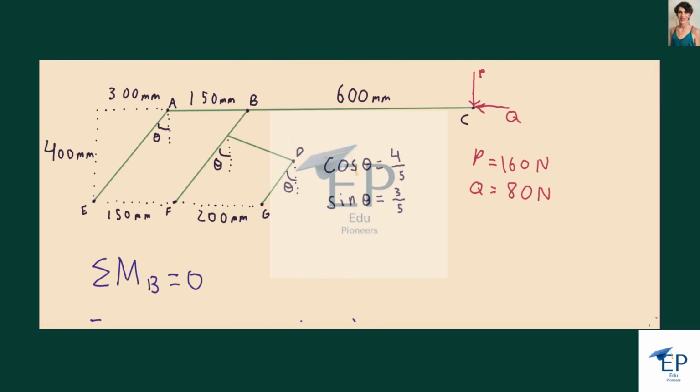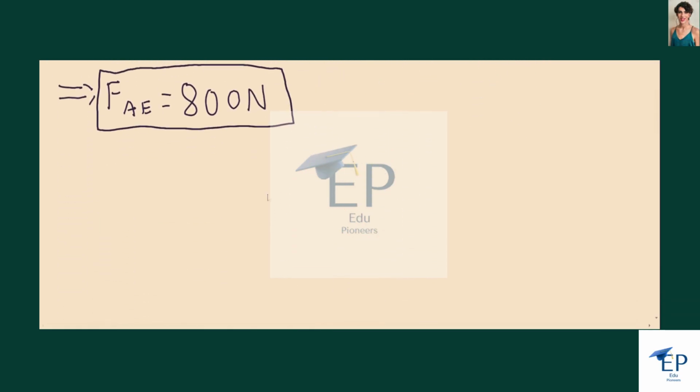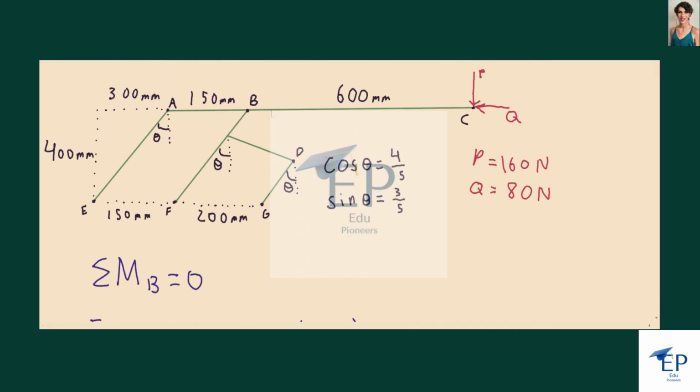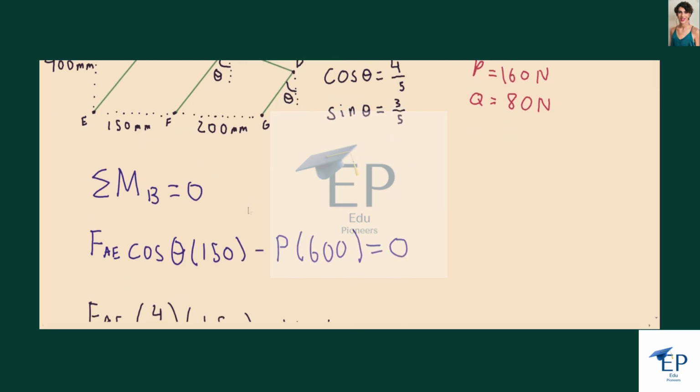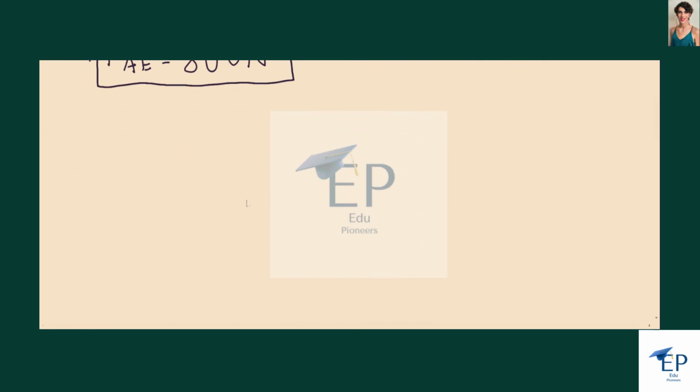So next we're going to find the force exerted on the spring DG. And to do that, we're going to first find the components of the forces that are exerted at the point B. And then we use that information to find the force on DG. So we'll start by saying that the sum of forces in the x direction is equal to 0.